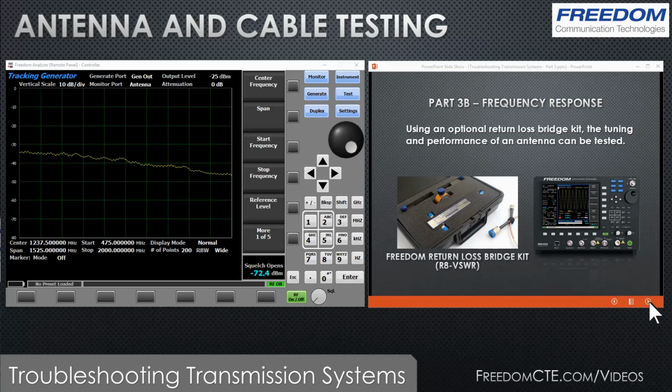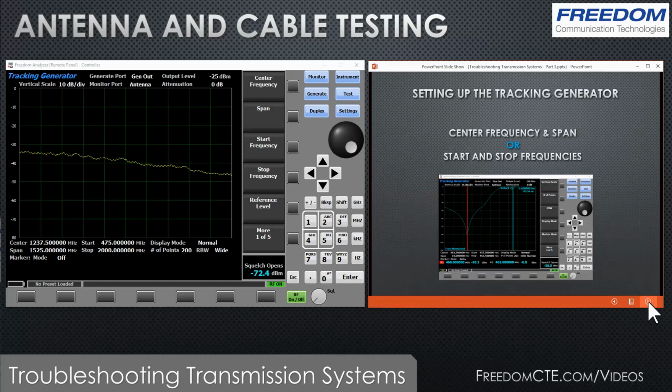In order to do this, we set up the tracking generator. For more details on using the tracking generator, see part 2 where we looked at tuning the duplexer. I'm going to move a little faster here, but the main thing right now is we need to set the center frequency and the span, or start and stop frequencies, to determine the area where we want to look.